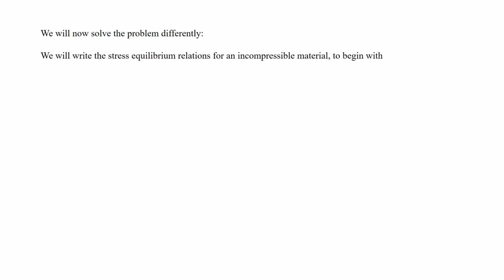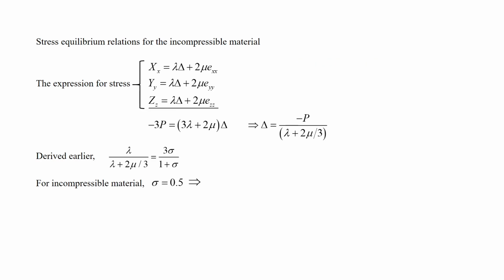We have considered an elastic film and we derived all the equations for the amount of load that needs to be applied to attain a certain amount of strain, longitudinal, along the thickness coordinate. So, that we did. Now we would like to consider that this film is an incompressible film. For an incompressible material we will write the stress equilibrium relations slightly differently, something like this. So, this is the expression for the stress.